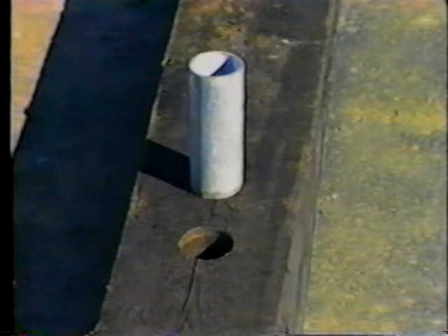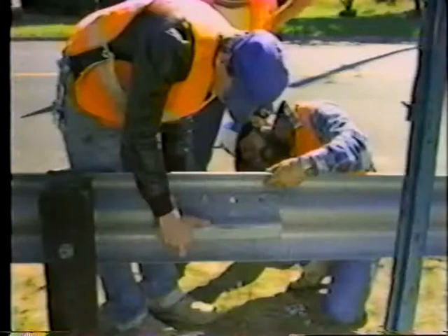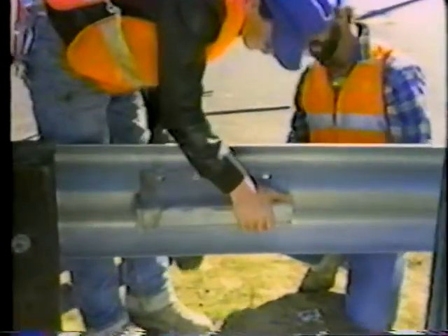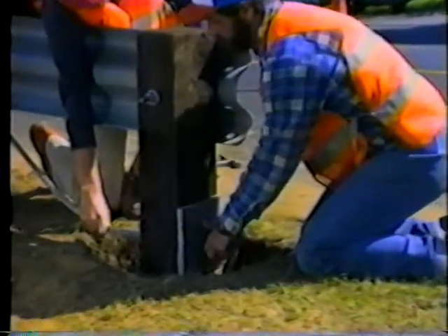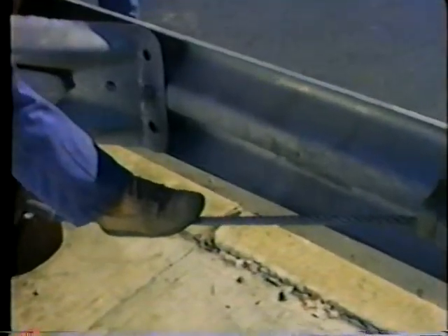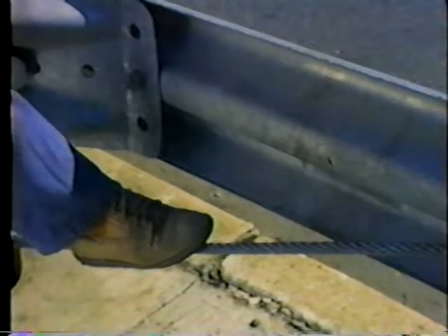The first post of both the wood and steel post BCT systems should be drilled with a 2 3/8 inch hole. On wood post systems, the cable, attached by 8 bolts to the back of the W-beam section ahead of the second post, passes through the first post and attaches with a plate to the front of that first post. A steel insert is used through the drilled hole to keep the cable from tearing the wood post. The cable must be kept tight. 3/4 of an inch of deflection is acceptable.